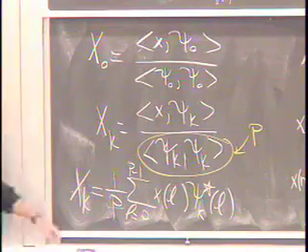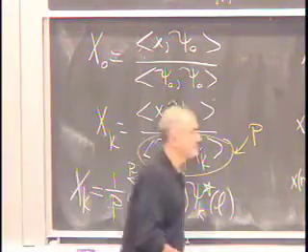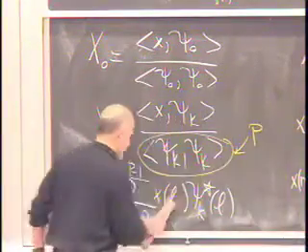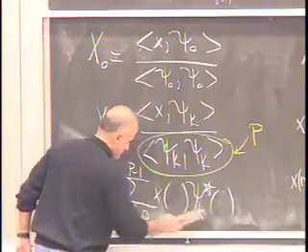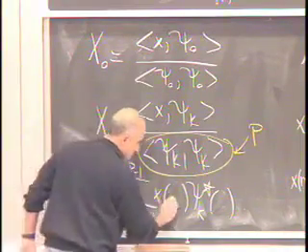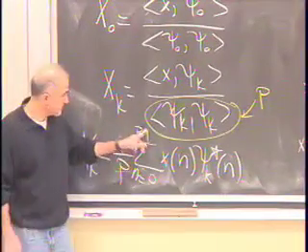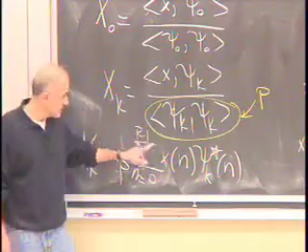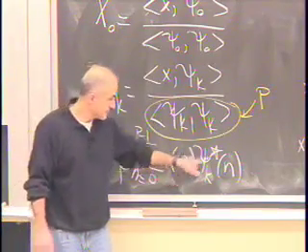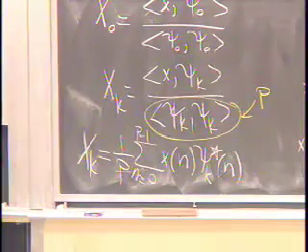Actually, because we have these in terms of n, we may as well just keep this as n. The inner product of x with ck is: you look at one interval, one period, and multiply the samples of the signal x, the first function, with the complex conjugate of the second function. That's what it is.